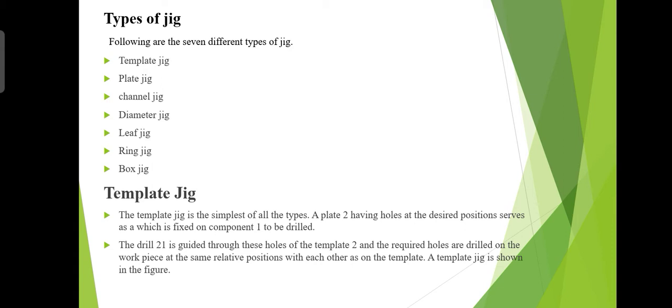Most commonly, manufacturers use the smaller jigs, as small parts are more numerous than large ones in any manufactured unit. Except in special cases, there must be a quantity of parts to be processed that have identical dimensions to make the use of a jig worthwhile. By providing locating surfaces or locating pins in the jig and clamping the part against them, critical dimensions can be controlled. These pins or surfaces must be hardened and ground to withstand wear in order to maintain the close tolerances.